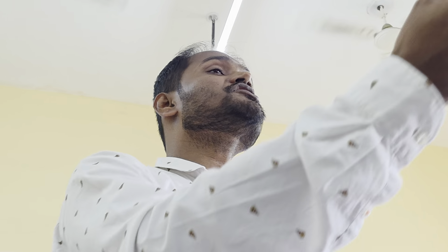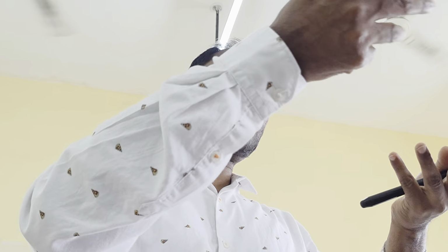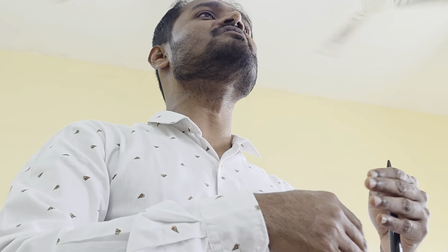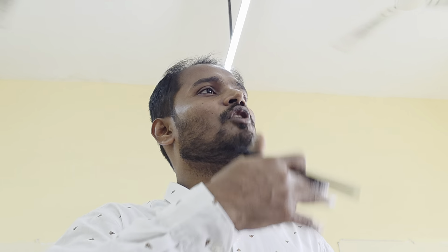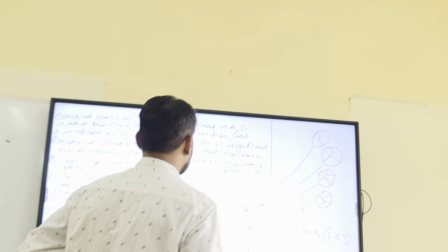So if a crack wants to initiate, the crack will not propagate. It will stop due to plastic deformation. Plastic deformation is due to ductility. And you need also strength now, because impact loading is there. Strength means resistance to deformation again. So both things are present in finer grain material. Okay. So that means exactly, if people know dislocation motion and all, at least you know, right? So if the grain is a coarse grain, what will happen if dislocation wants to move and you want to deform it? A time will come, a lot of dislocations will generate and they will pile up at the grain boundaries. You know all these things, right? Like this, right?